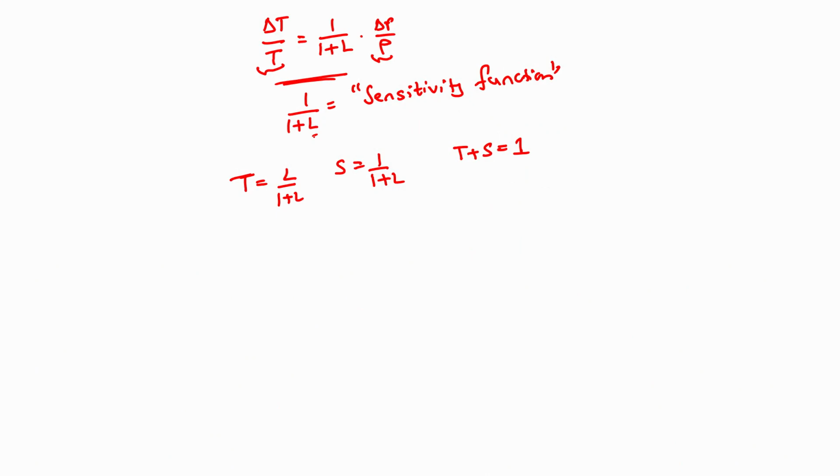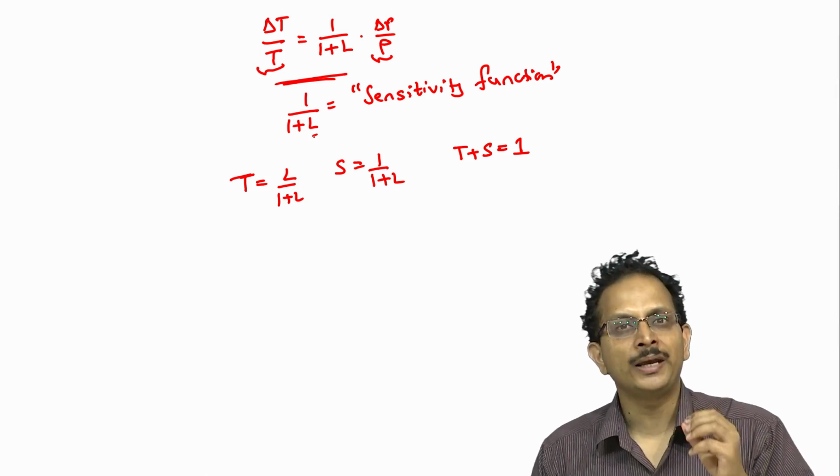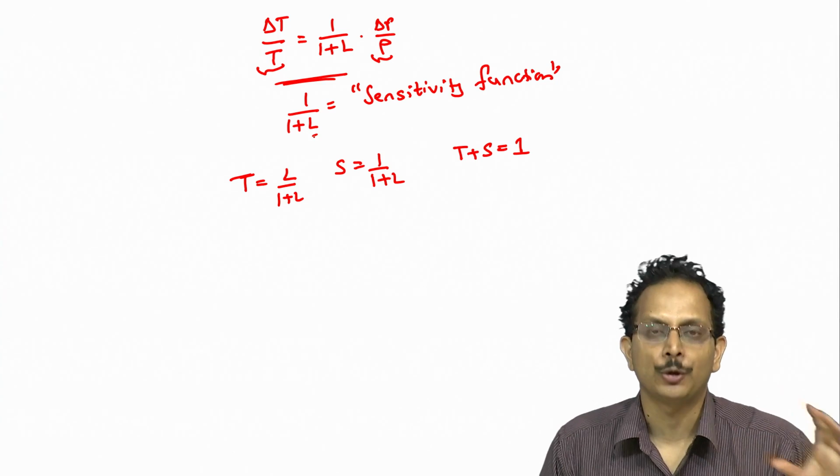frequency range. And if we take the logarithm of the sensitivity function, because if one were to try to draw the Bode plot of the sensitivity function, then we would note that in this frequency range, in the frequency range where we are expecting control performance, the logarithm of the sensitivity function is going to be a large negative number, because the sensitivity function itself is going to be a number that is very close to 0.